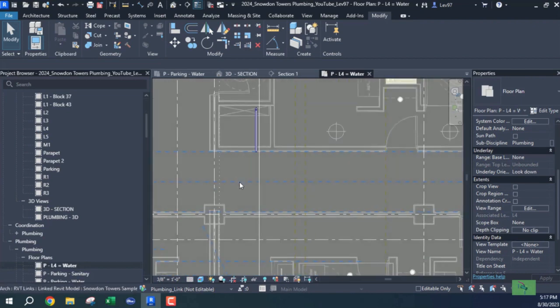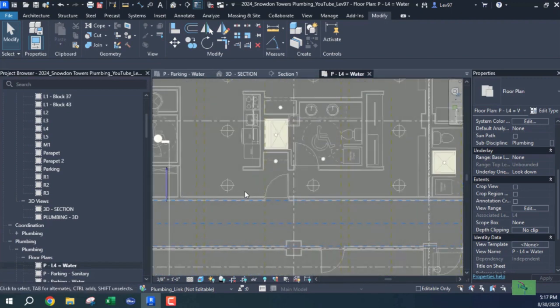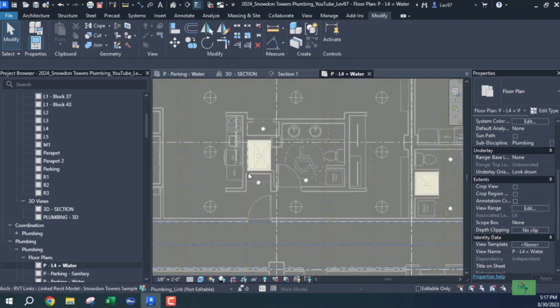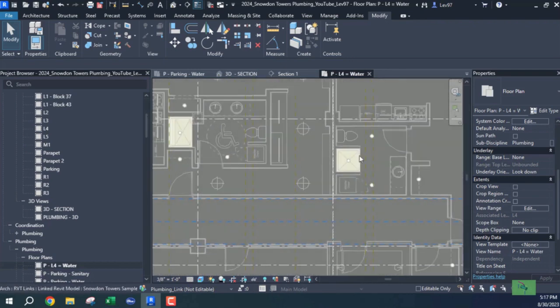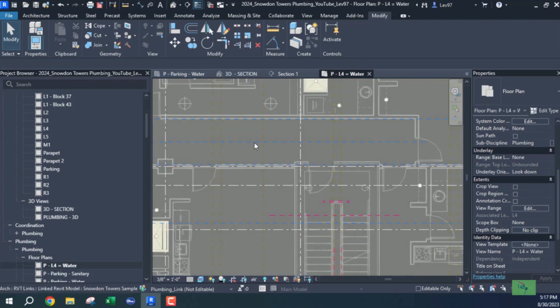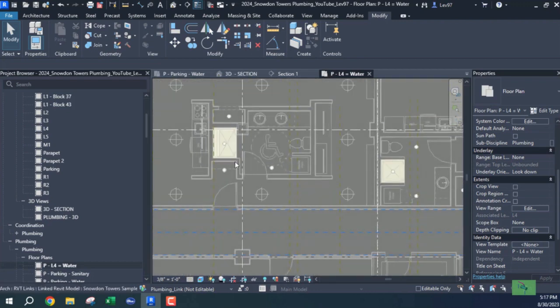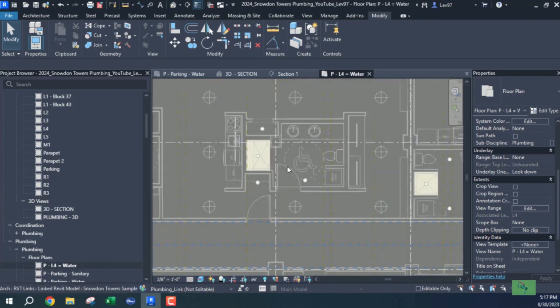Okay, so from here, as I continue, now that we got this 1-inch pipe up on the level 4, next what I need to do is take the hot water and the cold water and the hot water return, and supply these bathrooms with hot water, cold water, and hot water return. Looks like there's going to be some gas because of the tankless water heaters have some type of combustion going on with that flue going up through it.